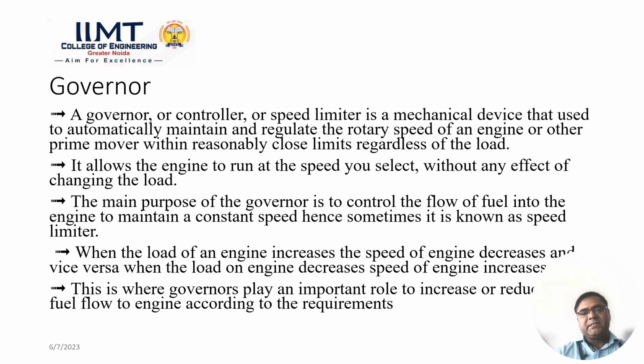There are basically two conditions. One condition is when the load on the engine increases, and another condition is when the load on the engine decreases. In the first condition, when the load on the engine increases, the speed decreases, and vice versa: when the load on the engine decreases, the speed increases. I have already discussed that the governor plays a very important role to increase or reduce the fuel flow to the engine according to the requirement inside the engine cylinder.